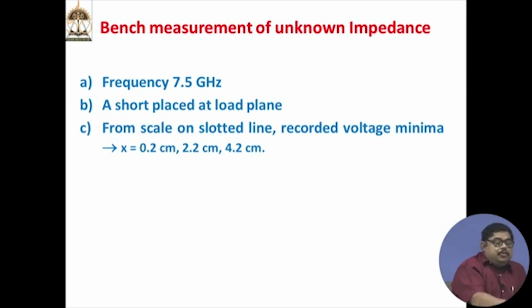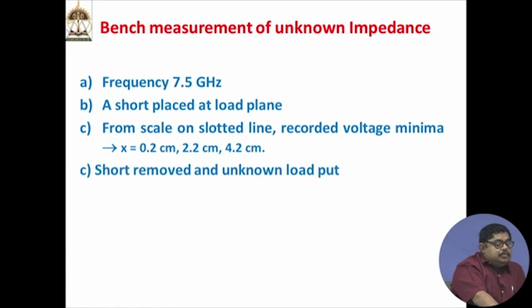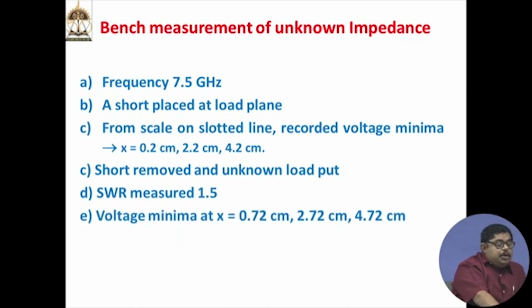Let us say we have done this experiment, and this is the recording of one of the students. When the short is placed at the load plane, the scale minima positions he has noted are like this. Short removed and unknown load put, the VSWR he measured by the method we said, let us say it is 1.5, and the voltage minima is shifted, so he has again found out this.